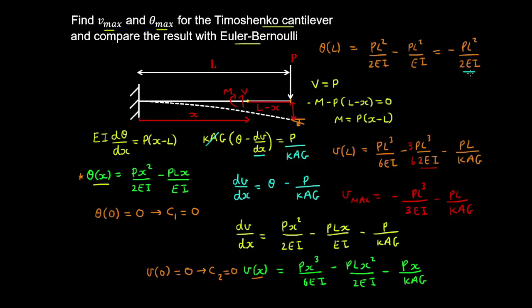And you can substitute for the rotation at x equals L into this expression to obtain a net rotation of the neutral axis, which includes the shear term.